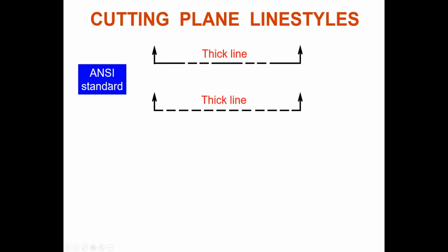For another drawing, ANSI, the American National Standard, they use a kind of hidden line. We don't practice like this. To me, if you make it a hidden line, it's worse, because sometimes your cutting section line overlaps with your hidden line. Sometimes we think it is a hidden line. But it is an ANSI standard. In our case, we use ISO, we use the typical center line.